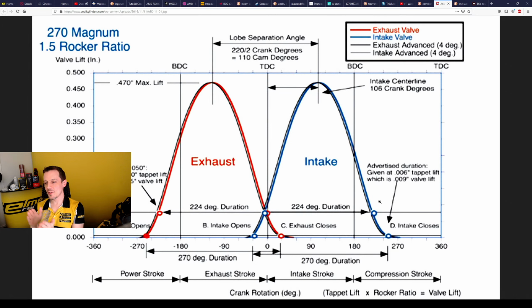I'm assuming to have some metered amount. So they probably have some pre-chamber with a specific amount of air at some specific pressure. They open a valve to allow that pressure into the pocket, actually opening the poppet valve then. And then you have a hydraulic system to dampen that movement and stop it at the desired height. And so probably need to have stable and then either steel or air spring to close the valve.